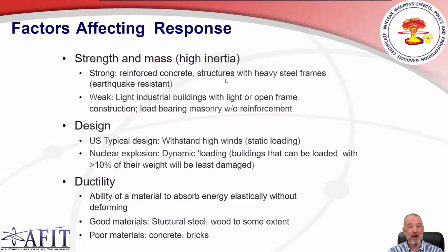But a concrete structure, it's not going to fail. The walls aren't going to collapse in. They're not going to crush in. You're not going to see the ceiling collapse. None of this is going to happen because it has the mass and the strength to withstand something like that. Similarly, for drag loading, again, if you have something that's really hard to push over, the more massive it is, the more difficult it would be to push. And so again, we have these heavy inertial structures and objects much better capable of resisting the effects of both portions of the incident blast wave.